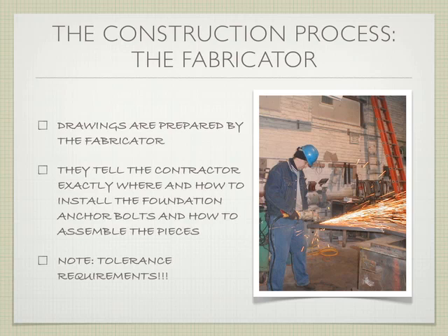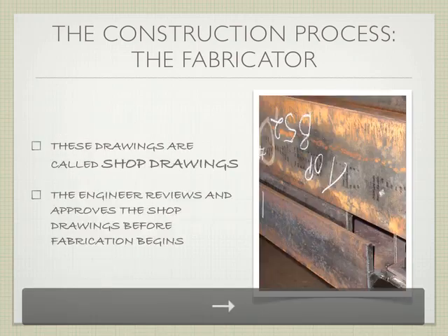You as the fabricator need to be able to drill all of those holes, right, and they're only a 16th larger than the diameter of the bolt, right? So you have to be so precise in how you fabricate all those things. So it's not like a fabricator's out there by hand, somebody's out there drilling holes, right? This is a very sophisticated process, high precision required. Certainly much more precision than, say, concrete would need to be, right?